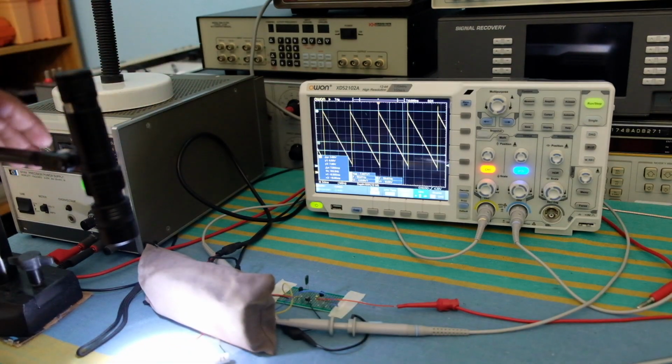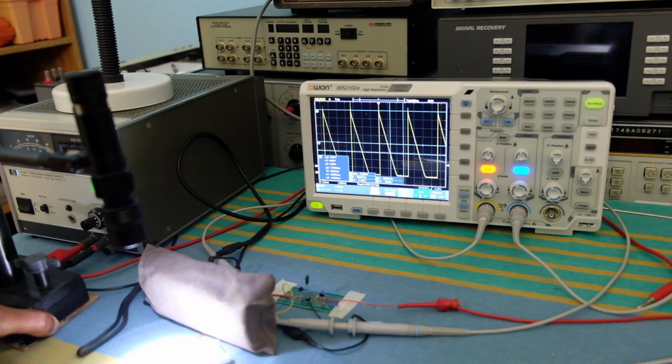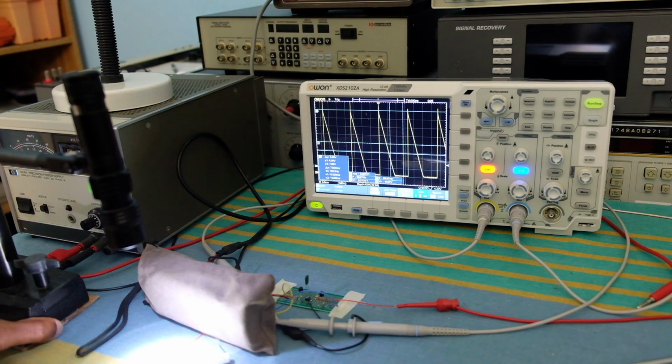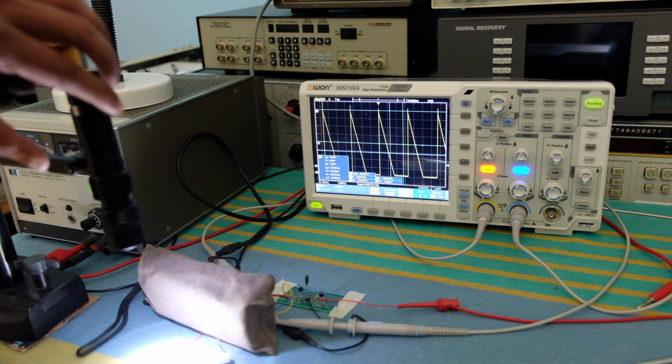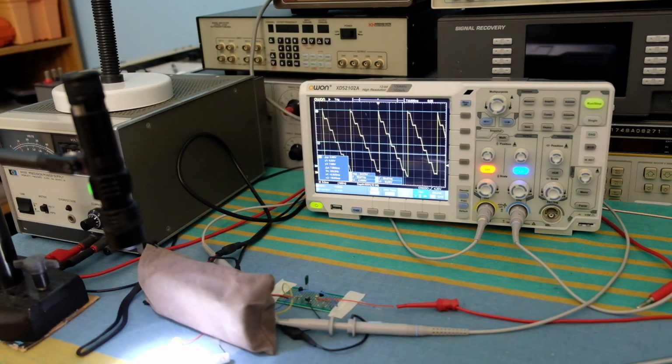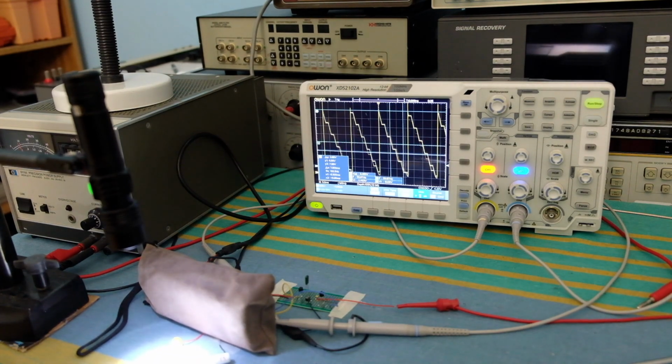So this is the full blast white light coming onto this LED, and as I move the light around, you can see the amount of intensity changes because of the angle or the distance or the focusing of the lens onto the photodiode, or the LED inside, which changes the current coming out. Now if I reduce the light using this position, there's something interesting happening over here: some modulation going on inside this flashlight, which is creating the dimming effect.